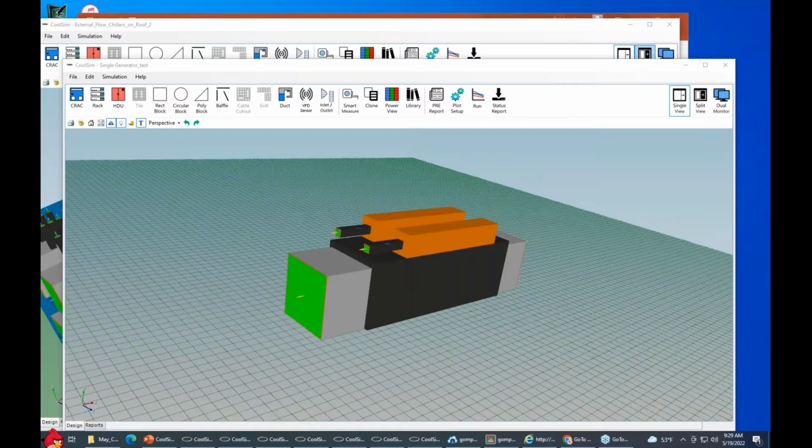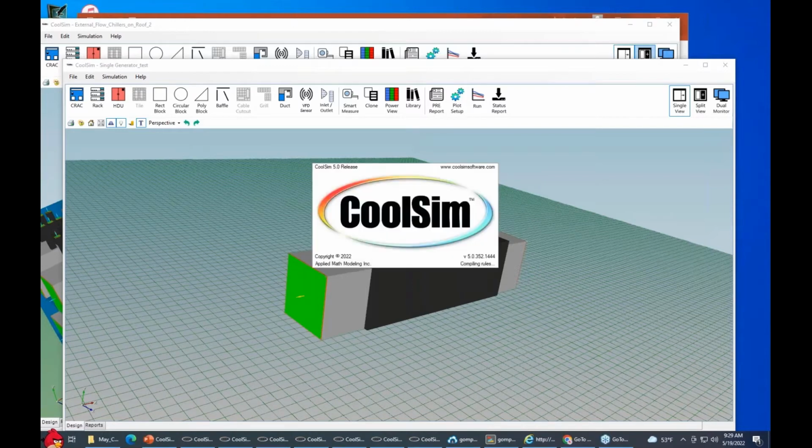In emergency cases, what often happens is that you'll want to bring air in from outside if you possibly can. So the model that I set up and will show you here is a case where we went outside and grabbed air. 2 things happened. One is on the hot side, we open louvers in the room and allow the air to escape.